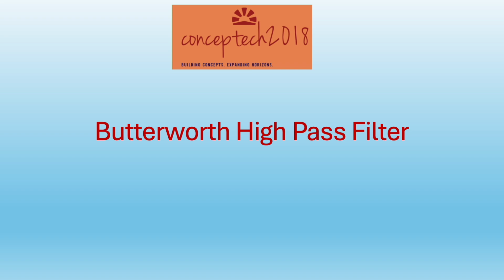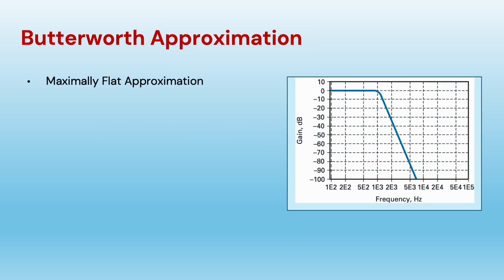This is the lab exercise on Butterworth high pass filter. The Butterworth filter is also called maximally flat approximation because the pass band attenuation is 0, so the pass band is flat. This particular response is for a sixth order filter where A max value is 2.5 dB and the cutoff frequency is 1 kHz. Here 1E2 means 1 into 10 to the power 2, 1E3 is 1 kHz, 1E4 is 10 kHz, 1 into 10 to the power 4 Hz.